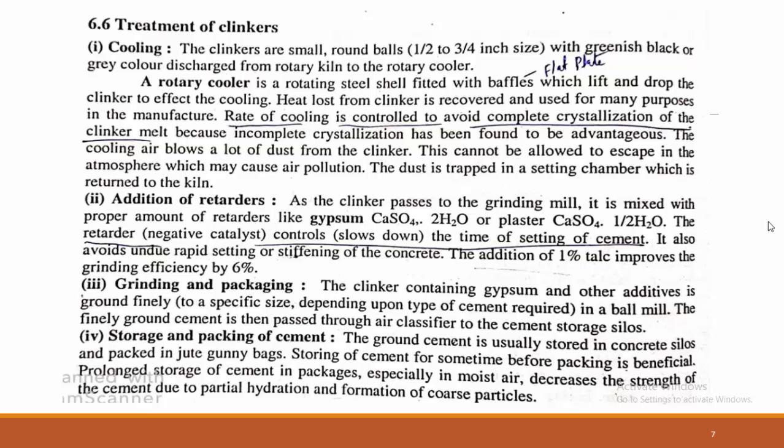It also avoids the rapid setting or stiffening of the concrete. The addition of 1% of talc improves the grinding efficiency by 6%. Sometimes gypsum is added, and powder talc is added for improving the efficiency as well as the setting time of the cement.